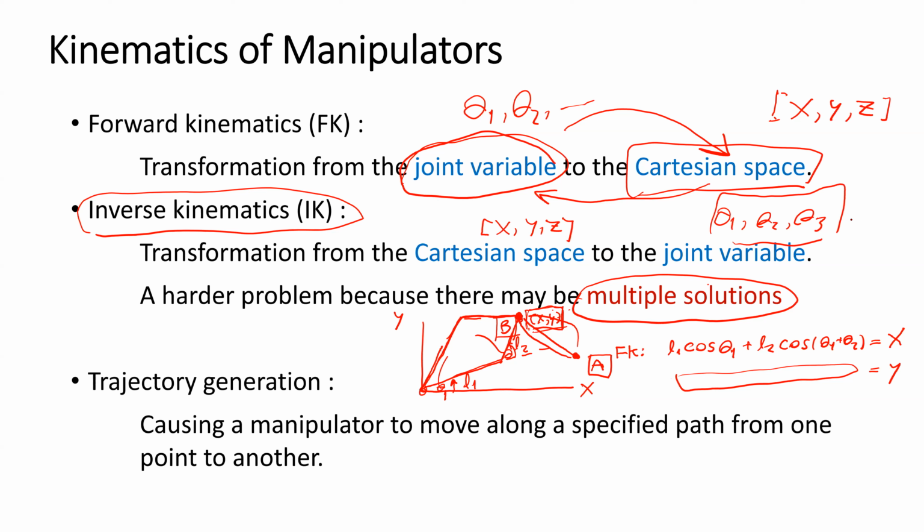The human likes that because the human can see the change in position, and many times they prefer the shortest XYZ move. But is that really good for the robot? Because the robot moves by theta 1, theta 2, theta 3.